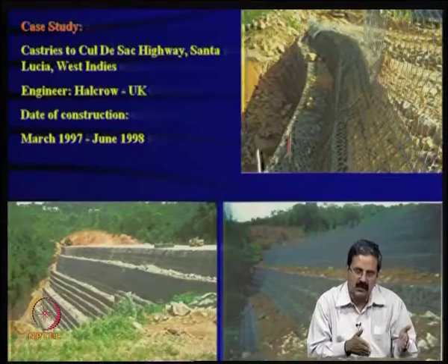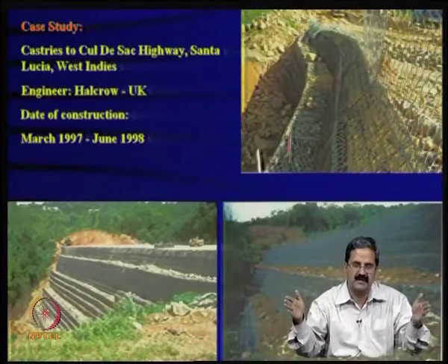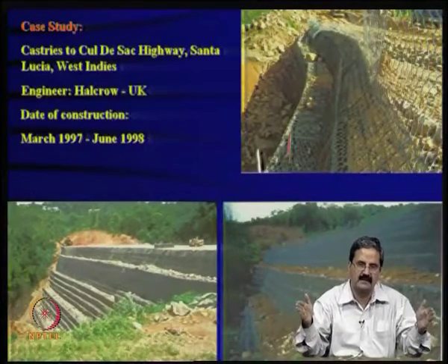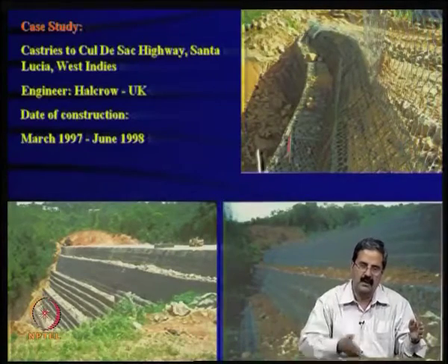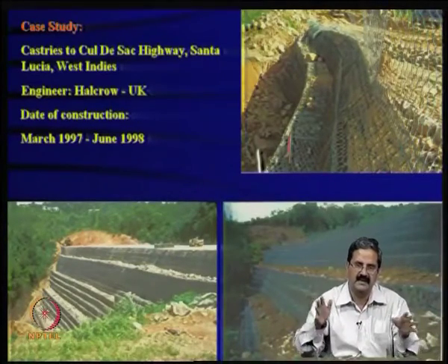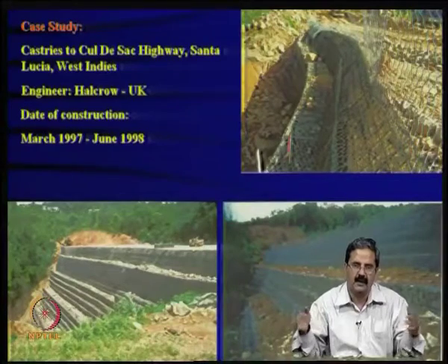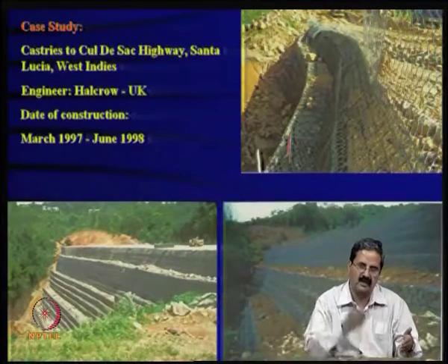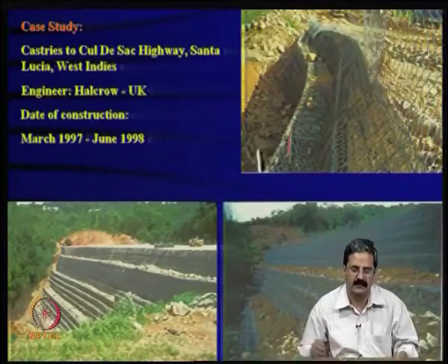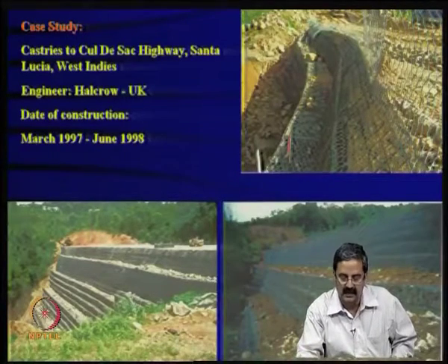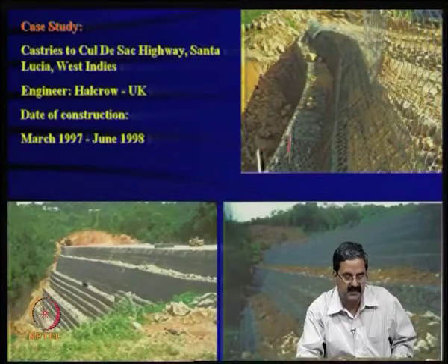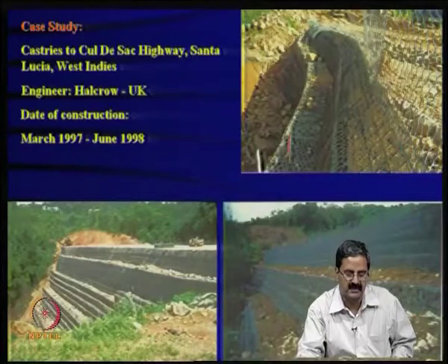You have to start from the bottom, and suppose you want to increase it to say 10 meters, you can identify the area, find out the backfill material, try to give a design, and it is possible. That is very important. And any type of facing materials can be used.